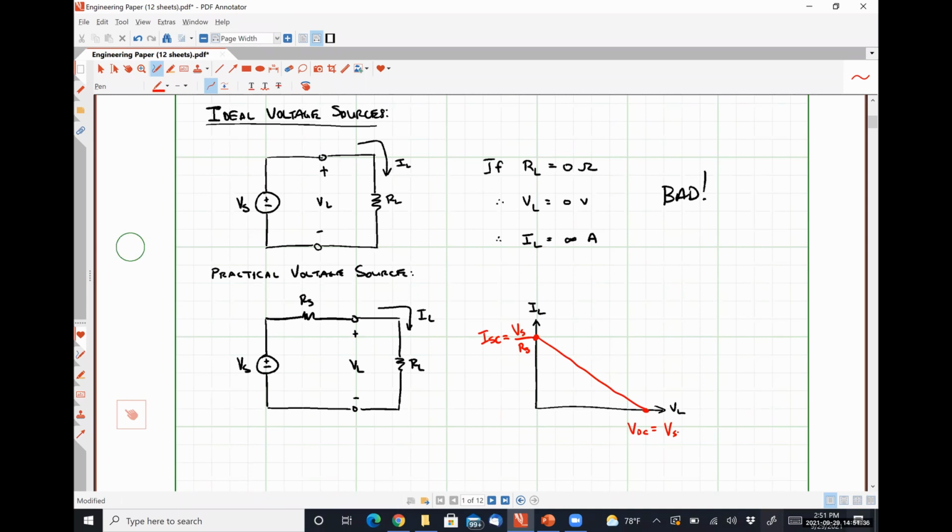In industry, those are the important parameters for a battery: short circuit current, open circuit voltage, internal resistance. That characterizes a battery. You don't need to know anything about how it's constructed. If you have those 3 parameters as an electrical engineer, you know everything you need to know about that battery.